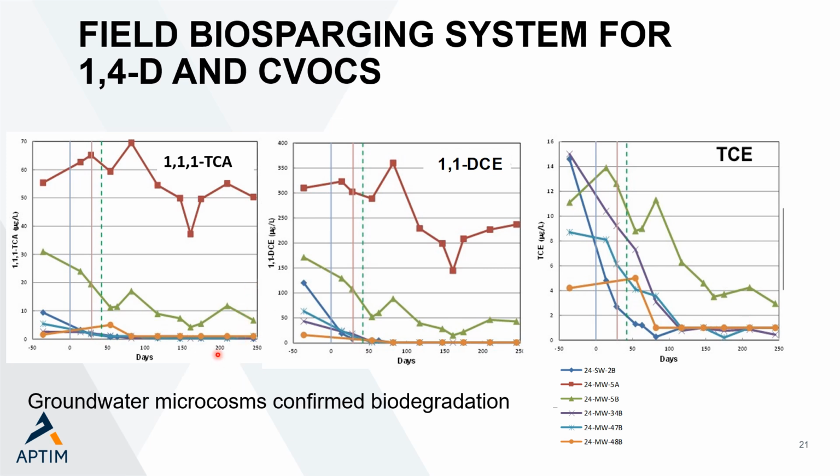I should note that samples were taken back to the laboratory just to show that this wasn't some type of sparging effect. And in fact, when nutrients and propane were added in the lab, all of these contaminants biodegraded.